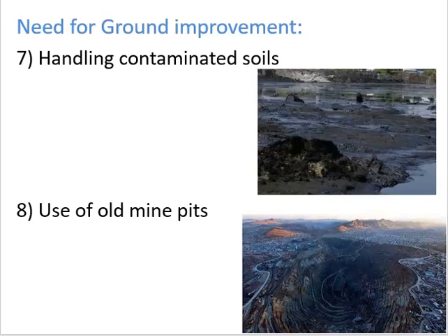Next point is use of old mine pits, to reuse the old mine pits for constructing buildings. The pits have to be refilled with soil, but the refilled soil has to be properly compacted to avoid settlement problems at the site. Before refilling, the site has to be cleaned by using a proper soil remediation technique, because the soil at the mining site contains harmful chemicals which were used during mining operations.